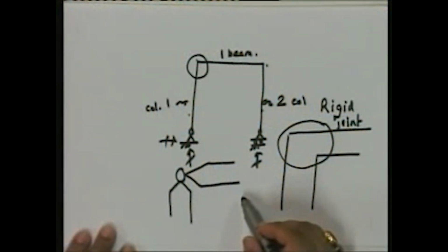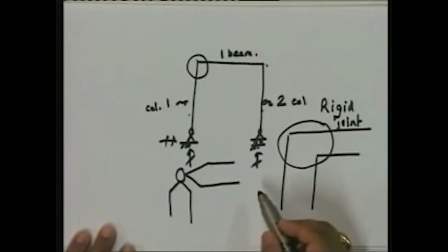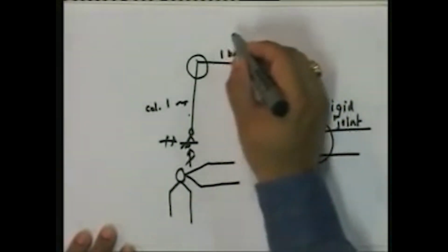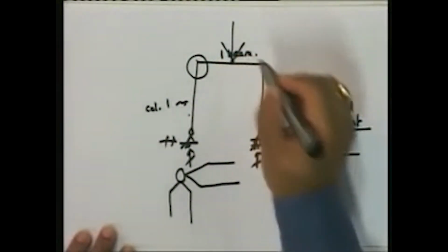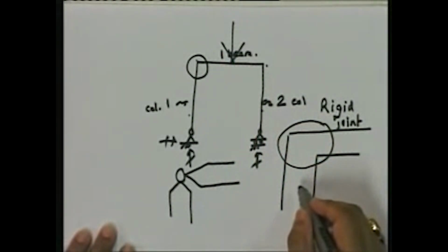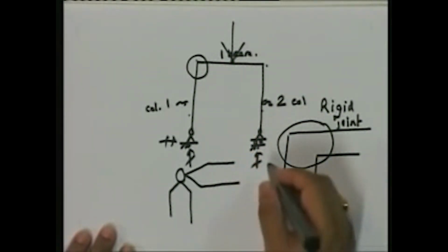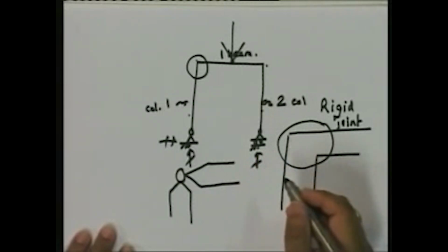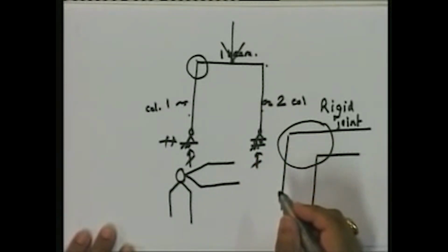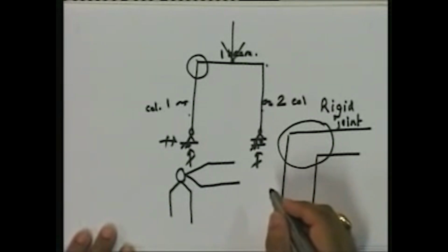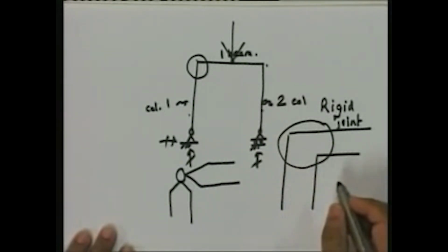Think about it. It's not. It's a perfectly valid frame. If I subject it to loads, let's say I subject it to a load here, is this structure going to move? Is it going to collapse? No, it's not. So obviously, the formula that I generated for a truss structure, m plus r minus 2j, is not valid for plane frame structures. Please understand this.